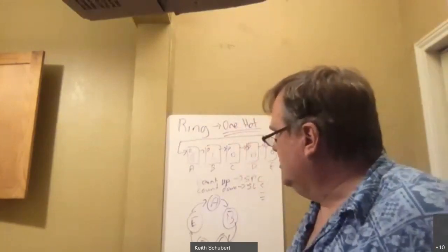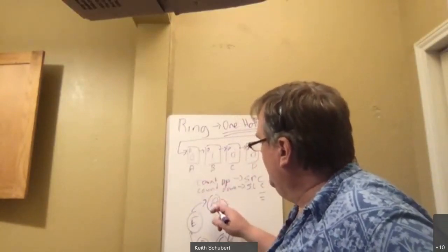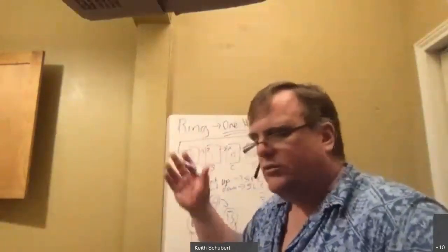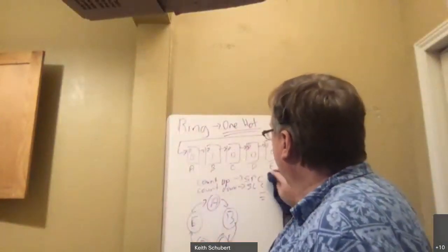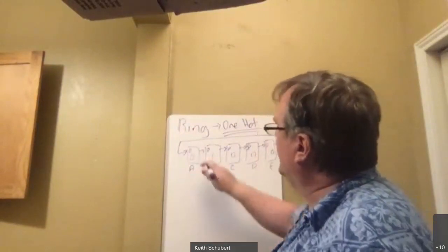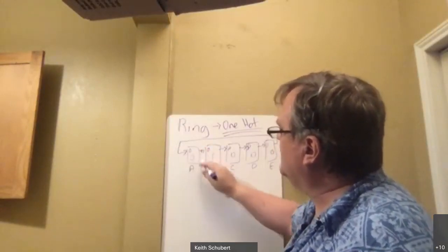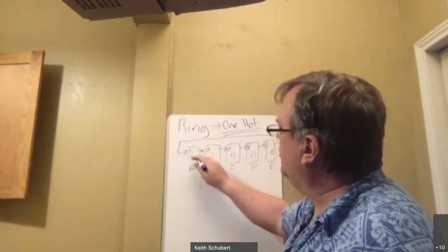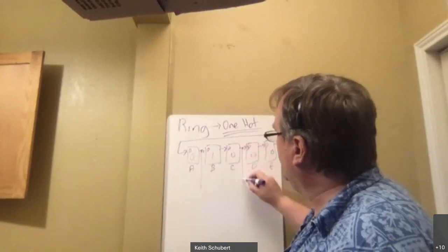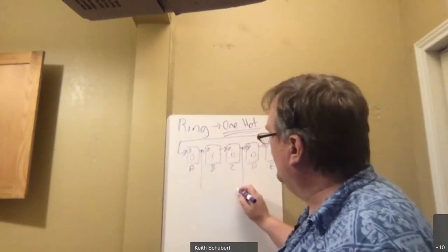I guess one final thing I could say, if you wanted to take a look at this and have some operation like, maybe in states A and C, I wanted to output a 1 for whatever reason, right? If I had to do that, to figure out what state I'm in, all I have to do is take this line and tap into it. Since this is state A, this wire will be a 1 if I'm in state A. And this is the output from the register that holds state C. So if there's a 1 here, I'll be in state C. Since there's only one 1, it'll only be in one location.